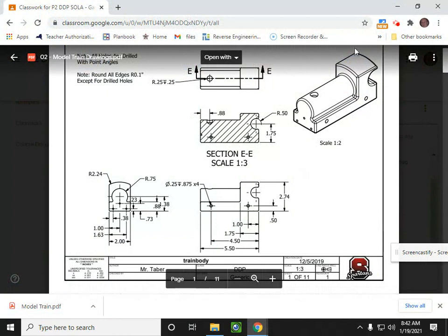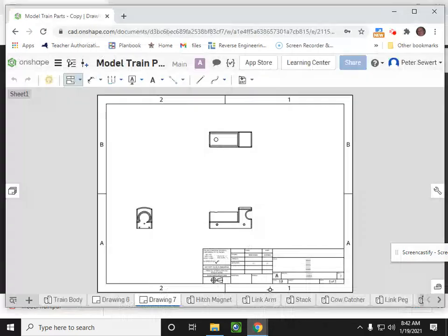I have 1 more up here. Well, I actually have 2 more that I need. But this is the isometric drawing up here. Now, I'm going to give you a little word of caution about the isometric drawing. Here we go. I'm going to go back with my insert tool on, and I'm going to click this front view. Notice all these views that I'm inserting come from the front view. Okay? They do not come from another view. They come from the front view.